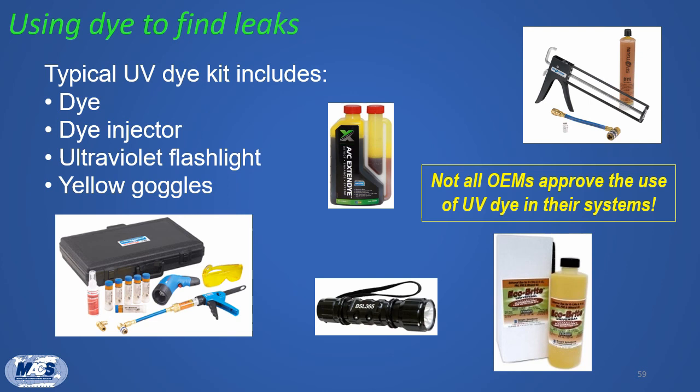Keep in mind, however, that not all vehicle OEMs recommend the use of UV dye in their systems, and in fact may consider dye to be a contaminant. Always check with the vehicle's service information and follow their recommended procedures. Remember too that dye mixes into the refrigerant oil and refrigerant carries the oil around inside the system. In order for dye to be effective, a full system refrigerant charge is required.